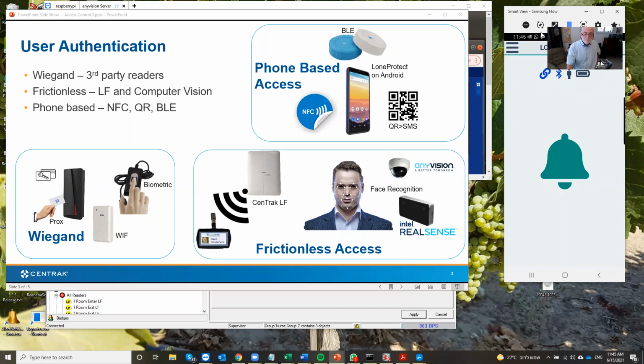Okay, so Omni, typically the CCTV integration that we have in most of the sites, and we have a lot of them, is where we use the API from the CCTV system to share with them the events in Omni. So you can assign a CCTV channel value to a reader in Omni. So when you have the alert at a particular reader, it will send a message to the CCTV system containing that channel, saying, okay, pop up camera number 5.